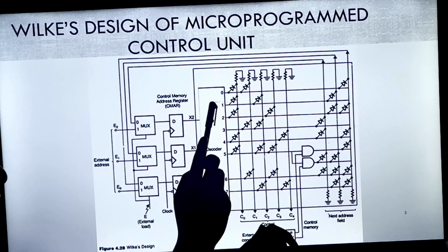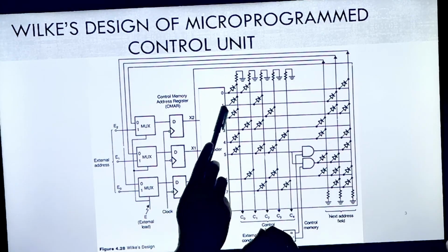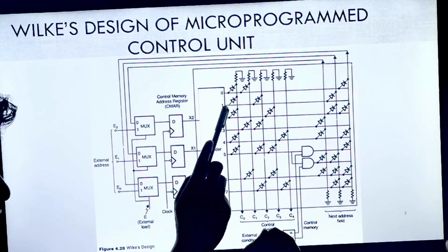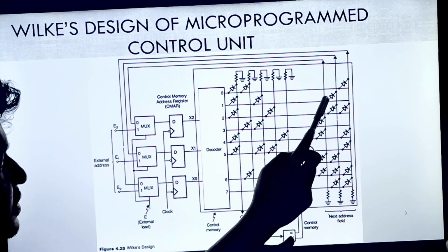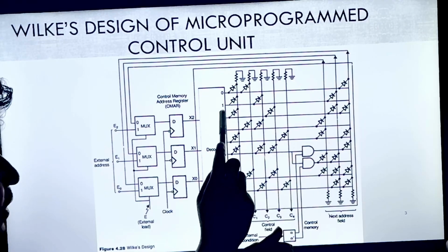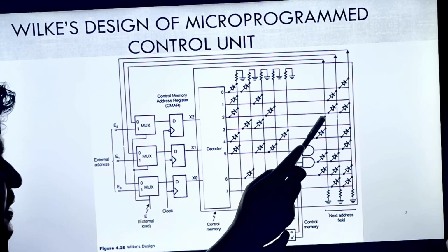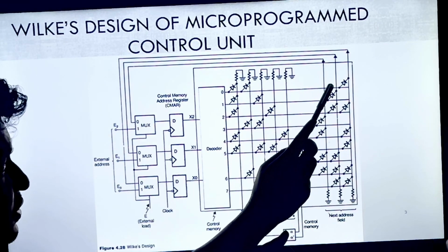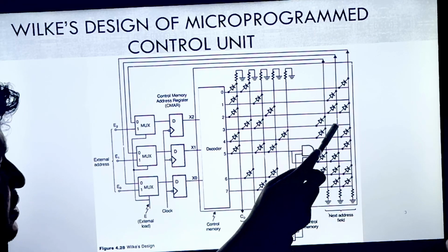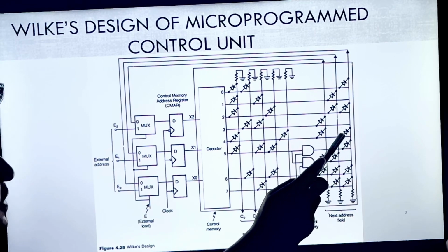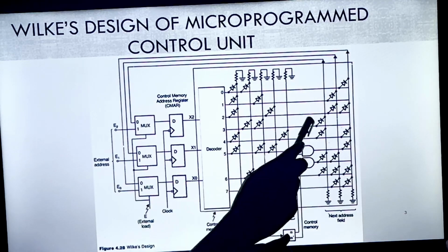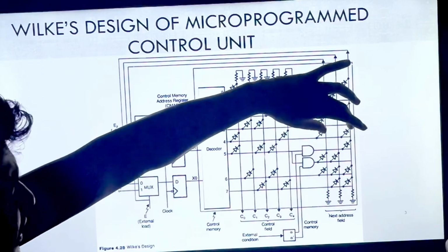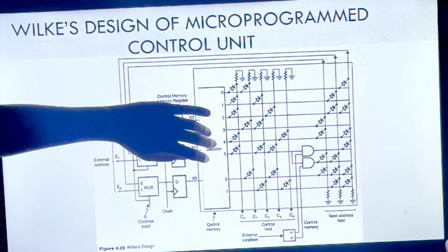When I am executing the first state, the next state I shall execute is 0, 1, 0, which means the second one. When I am executing the second, the next state should be 0, 1, 1. So sequentially I am telling my decoder to execute the next state. So this is how it will tell the decoder which one is the next state.